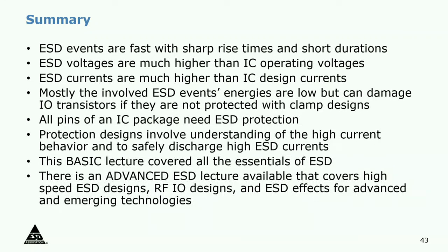I've got a 6-year-old laptop, and I think it has some of these problems. Your 6-year-old laptop is more about hot carriers and slowing down of the transistors. It wasn't hit by lightning. But when you say the failures, that's returned within the first year? From IC chips that are returned from the customers. The customer says the system failed, this is the chip that failed, I want you to find out why this chip has failed in my system. That's like within weeks or months of them buying the chip. Right, okay. I didn't know what that meant.